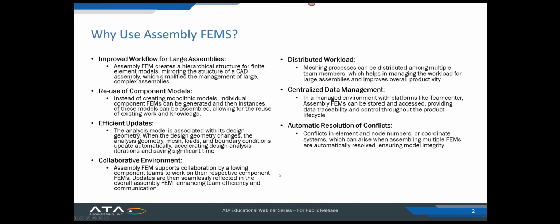Collaborative environment and distributed workload. These are two other aspects that are also really important and really useful for assembly FEMs. Usually, if you were to just set up a single FEM for an entire assembly, you essentially can just have one user have that finite element model open at one time. But by leveraging assembly FEMs, you're able to break up that assembly into sub-assemblies or sub-components, and then have people working on those individual FEMs in tandem.